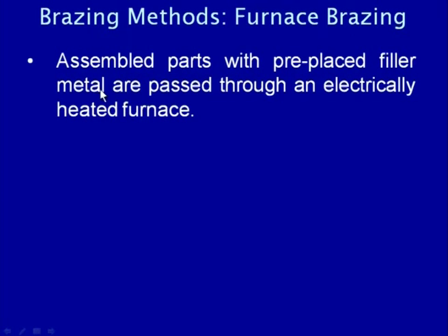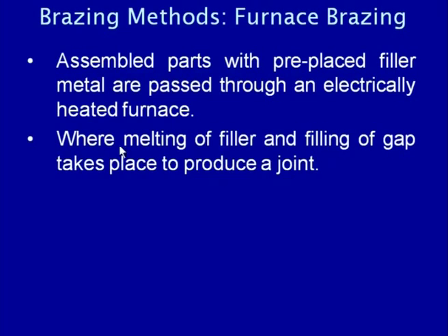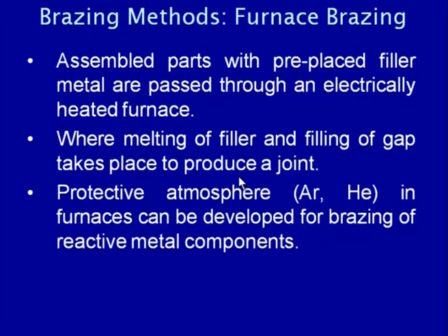In the furnace brazing, assembled parts with a pre-placed filler metal are passed through an electrically heated furnace where melting of the filler metal takes place, which in turn fills the gap between the components to be joined in order to produce the joint between the components. A protective atmosphere like helium and argon in the furnace can be developed for brazing of reactive metal components, so that unnecessary reactions can be avoided.